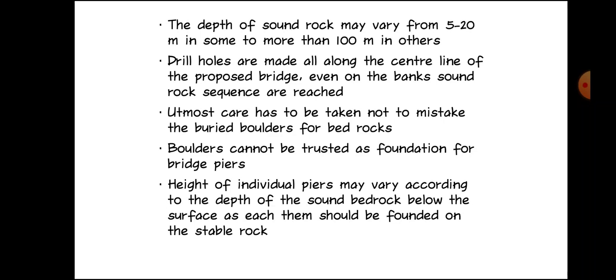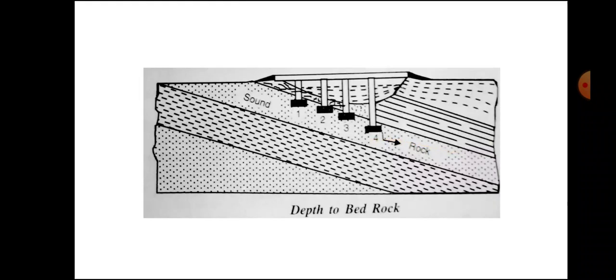Even on the banks, sound rock sequences are reached. Utmost care has to be taken not to mistake buried boulders for bedrock. Boulders cannot be trusted as foundation for bridge piers. The height of individual piers may vary according to the depth of the sound bedrock below the surface, as they should be founded on the stable rock.